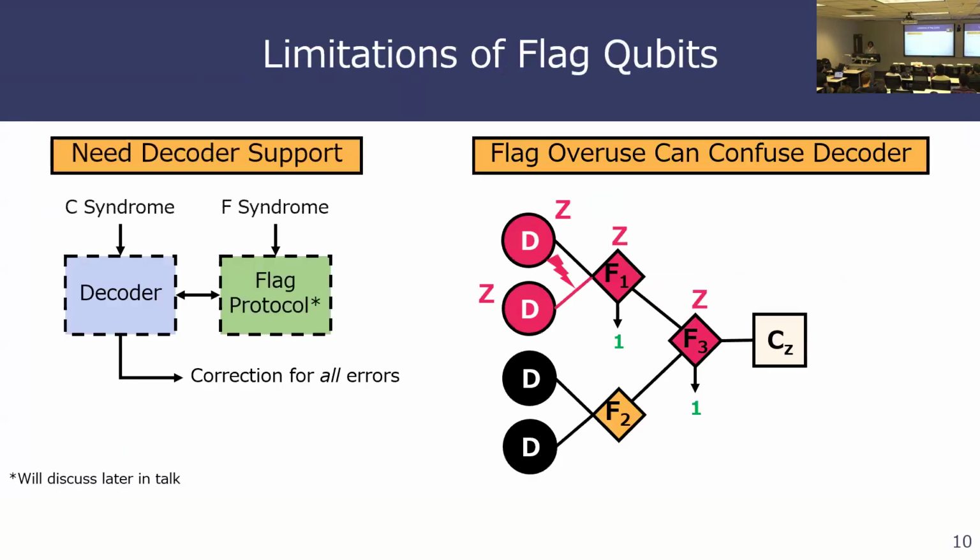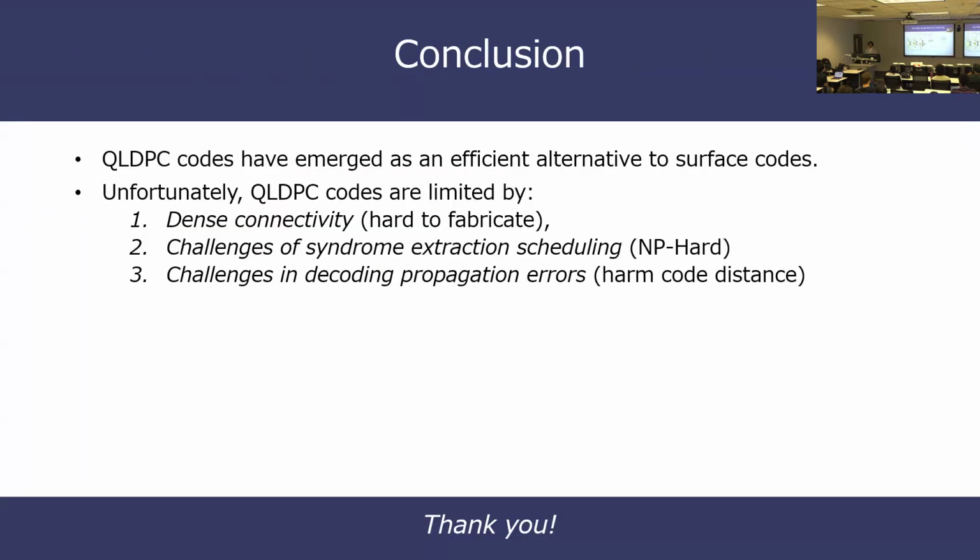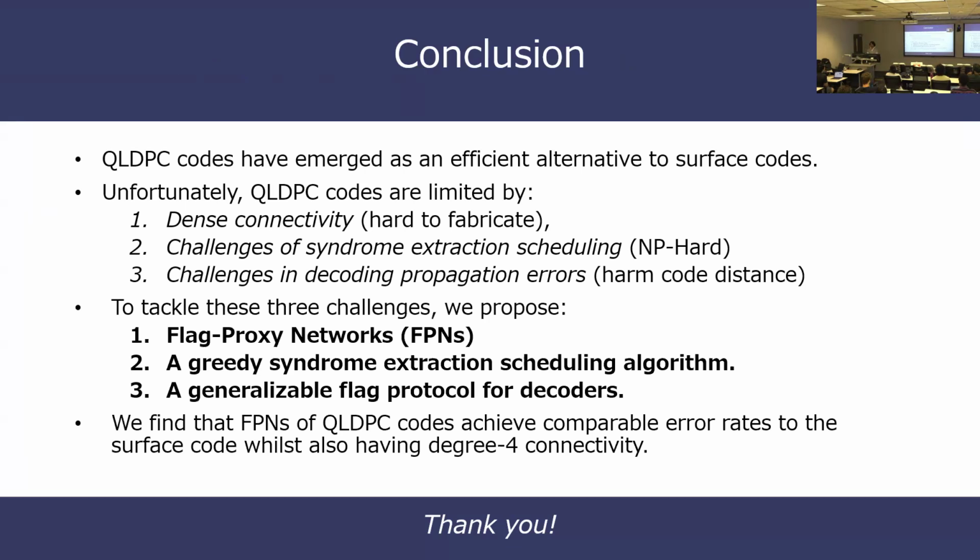Now, regarding what kind of support you need from your superconducting hardware, one of the big issues about QLDPC codes in superconducting computers is that they're non-planar. So I can't manufacture them with existing superconducting hardware. What I will need is another layer on top where I can have long-range couplings. I haven't really talked about that here because everything is biplanar for these codes, and it's not interesting to talk about, but that is a consideration.